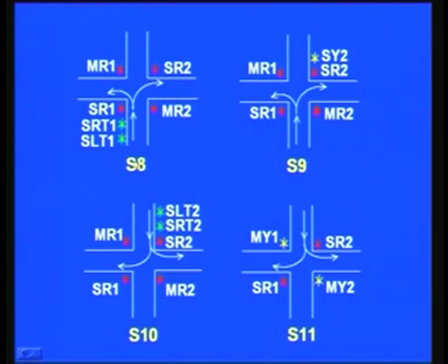Side road 1 is allowed here, and once again a yellow transition, and in this case it is only yellow for this because next is going to be right traffic as well as left traffic flow on this side, as far as side 2 is concerned. All other things I do not have to explain here, they are naturally red, and whatever is to be done has been done.